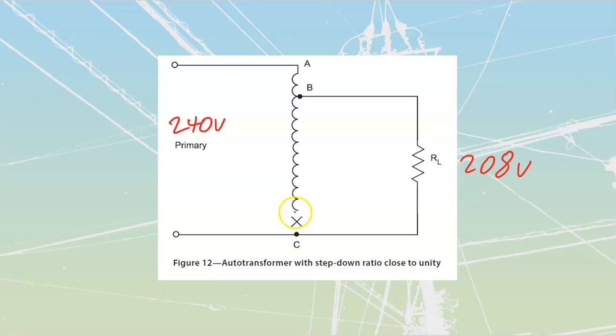If we have something like this where we've got a good transformer, and I'll be honest, it's pretty rare that the transformer windings fail. Usually it's going to be your connections as an electrician, where you're tying these things into lugs and threading them together on small transformers, that are going to fail. But if this connection were to fail, what we end up with is an unrestricted stinger that's just basically going to be hanging out over top of here.